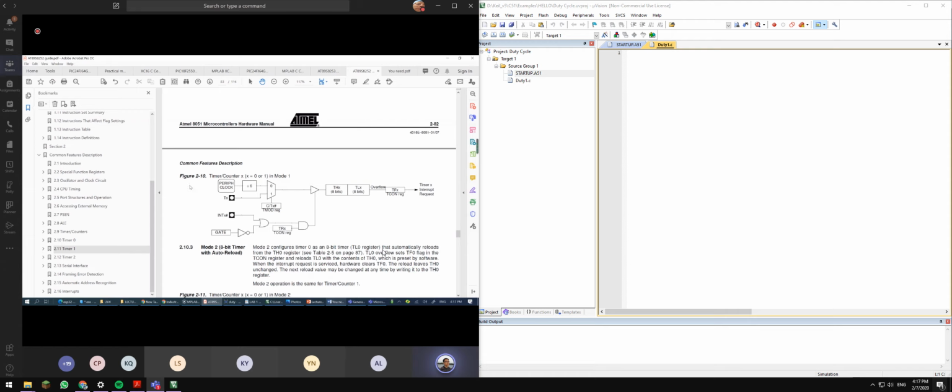Let's say, for example, I am using a 12 megahertz crystal, this is FOSC. For Atmel it is slightly slower. So FCYC is 12 megahertz divided by 12, which gives you 1 megahertz. Remember, the most popular crystal frequency used in Atmel is actually 11.0592 megahertz, so the period is 1.085 microseconds. Why is this important? Because by using this value, you get a very accurate baud rate. But for testing purposes, I assume it's 12 megahertz, so it gives you 1 microsecond.